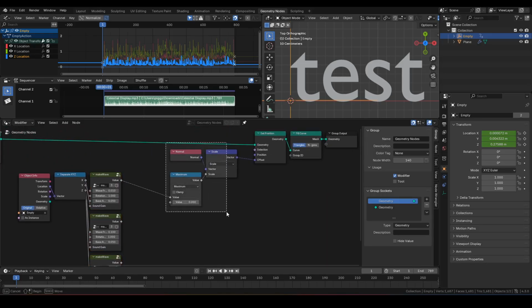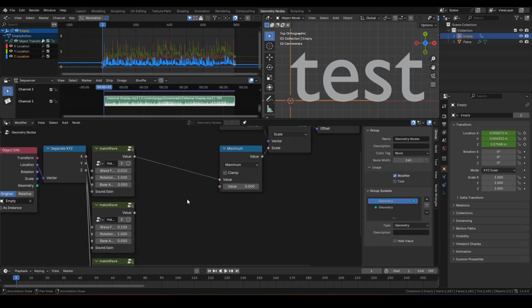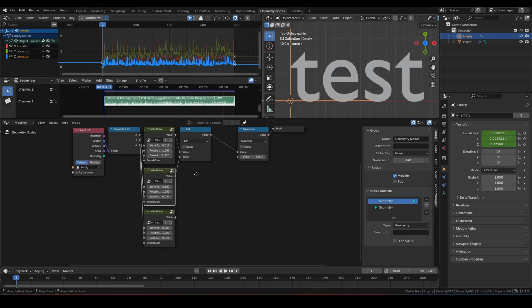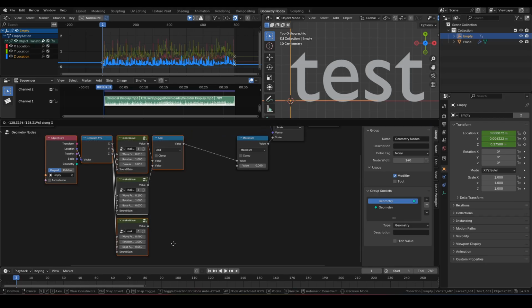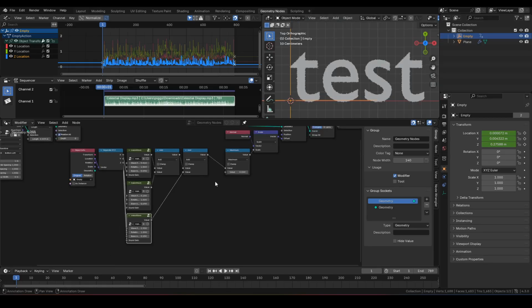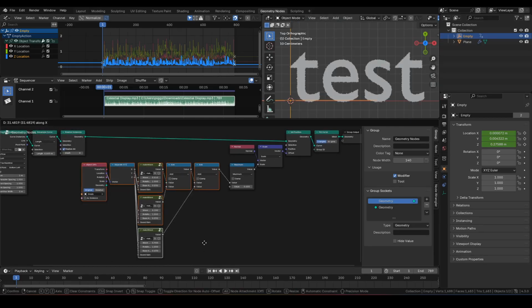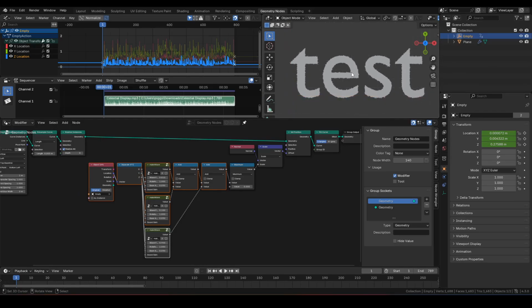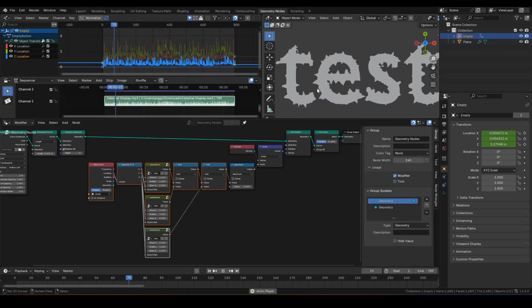With that done, let's add them together by using a math add. Add the mid-range, and also let's add the high noise range. Okay, like so. Right. So if I were to run the animation now, you can see there's a different size of spikes and bounces.